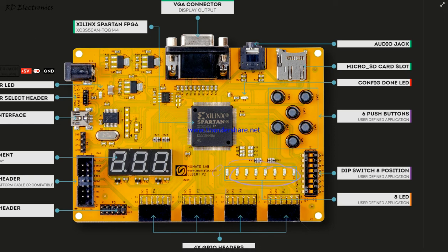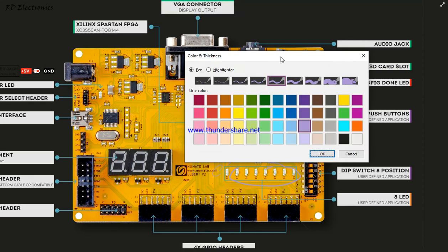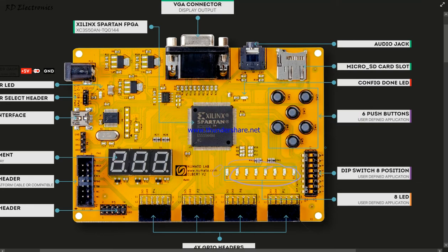There are also many features available on the FPGA, like these 4 GPIO ports and 1 JTAG port, Joint Test Action Group, where 4 or 5 signals are used for debugging and running the core FPGA chip. 3 seven-segment displays are connected, and this is the FTDI IC, which is connected via USB to the computer to download the hex file to the FPGA board.